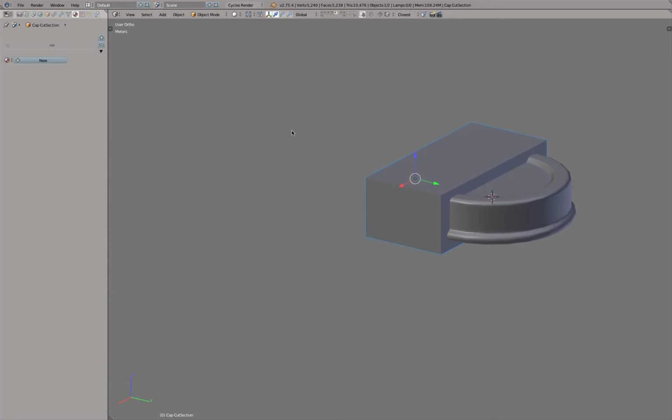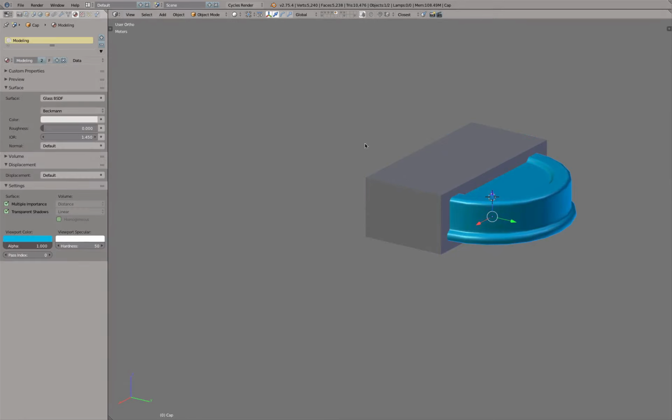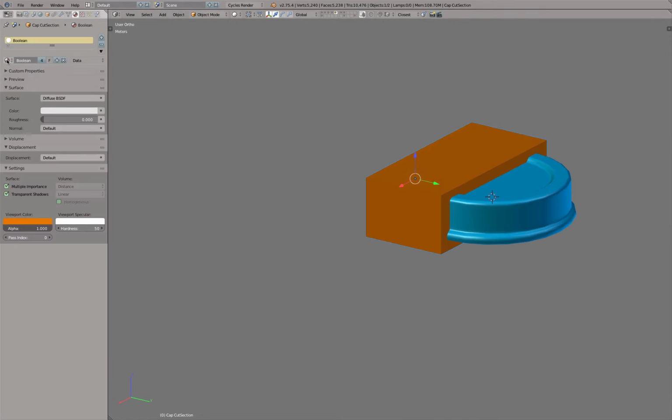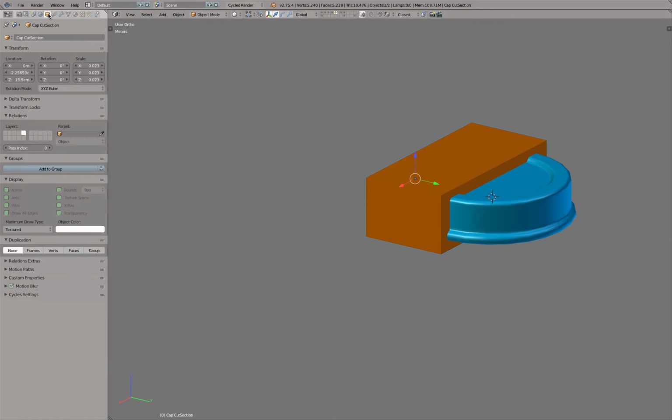And yeah, so why? The main reason is now with this cube I can cut this one area out. But you see I gave everything the colors, but this cube is visible all the time. I can simply go to the object properties, go to display, and say, instead of showing it shaded all the time, just show me it as the wire model.